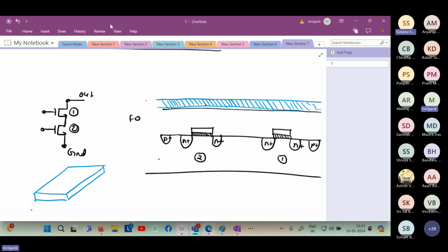Sir, hello. I wanted to ask one thing. You said that there are many metal layers separated by the oxides. Do these contribute any extra capacitances for the chip? There will be some capacitances which will come because of the interconnect, that I will discuss. That is not directly with the MOSFET, but that will be related to the capacitances of the interconnect.